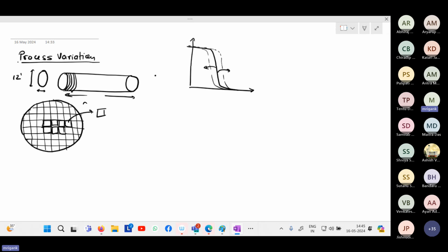So this is called dicing. This is silicon ingot. This is wafer. And from there, this is a die. So after dicing, you cut and get the individual chips, which are the silicon chips on which your circuit is fabricated. So when you do a single design, you may get multiple copies.